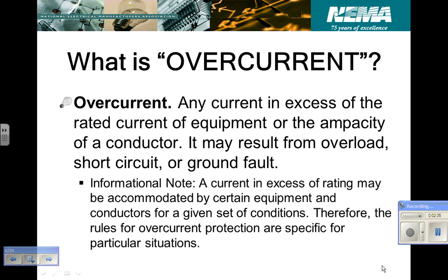The short circuit is literally a dead short, and it happens very quickly. The definition of a short circuit, remember, is a short between two energized conductors, and that includes a neutral conductor where it's an energized conductor. A ground fault is a different classification. It's still a short circuit, but it's where the short circuit goes from a hot, energized conductor to anything except another energized conductor, including neutrals. It goes to the conduit, the grounding conductor, the frame, a fence, dirt, water, anything except another energized conductor. That is a ground fault.